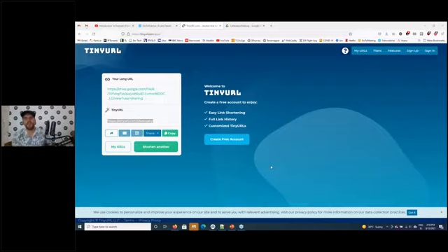Yes, I would recommend you to first do a calibration project. So you can do calibration the same way we did it for drones. You can put some targets on a facade and then record images of these targets from various angles in order to get the best calibration parameters. Alternatively, you can also use this calibration field. Both of these things will work.